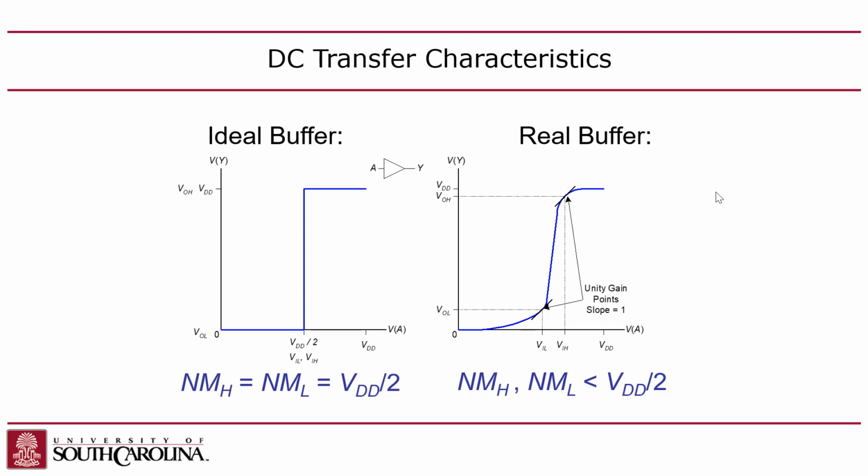And then suddenly it'll fly up, at VIH, when I set the input voltage to VIH, which might be, say, 600 millivolts, then the VOH will be pretty high, right? It's not going to be all the way at the top, but it's going to be pretty high, and that's your VOH, right? So the implication of this is that this gives you a noise margin.